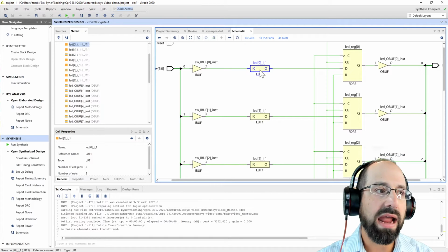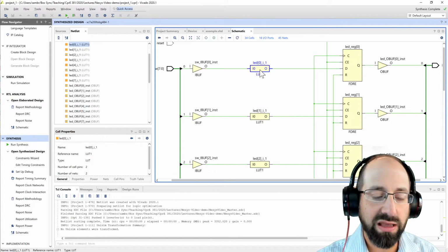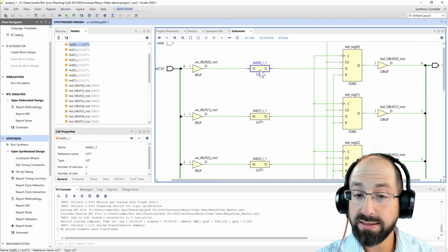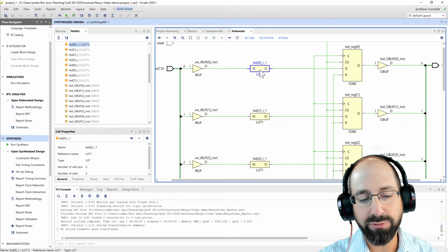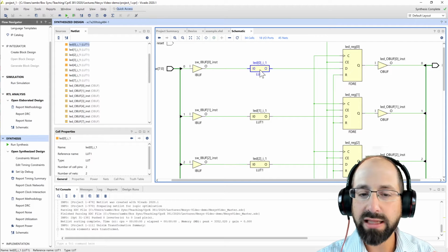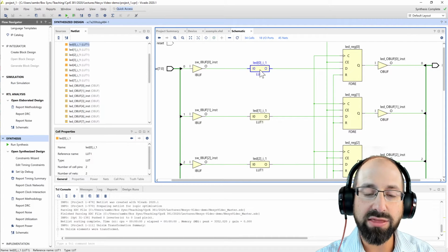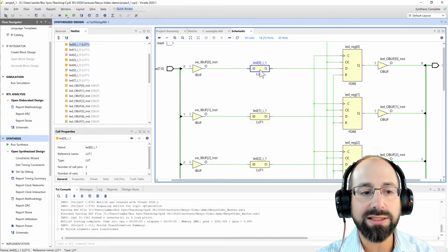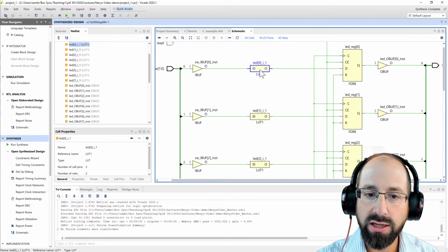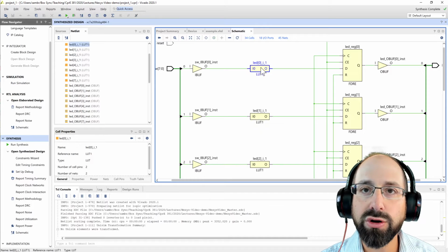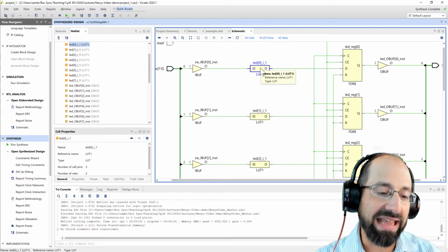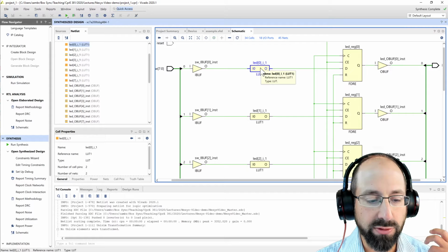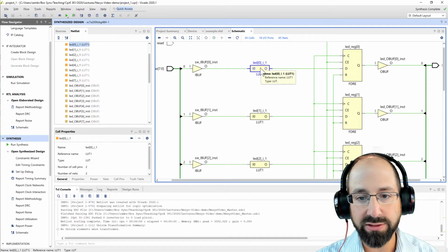And it's storing effectively the truth table for your function. It takes inputs, where the truth table tells you the ones and zeros for that function, like we've drawn out a million times. And the way these devices are reprogrammable is because they're just little SRAM memories storing truth tables. If you want to change this from an inverter to an AND gate, all you have to do is reprogram those SRAM values, those little memories.